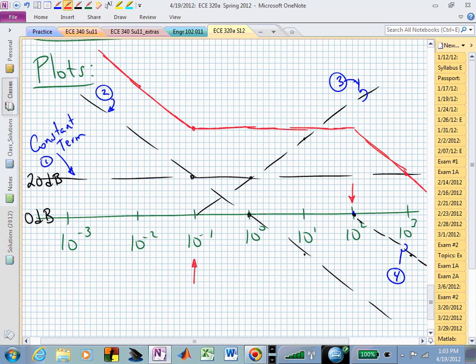So now you inject a signal, and now here's another thing that'll be the final exam question. You've now sketched this Bode plot, and somebody says, oh, what's the response if I inject a sinusoid into this system? Meaning, if I now put in a sine wave, or let me put in a cosine wave, let's just say it's 2 cosine of 1t. What's the output response going to be in the sinusoidal steady state? This tells you for all frequencies what's going to happen. You say, oh, what was the frequency again? 1 radian per second. You find 1 radian per second.